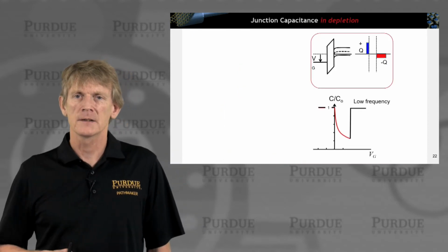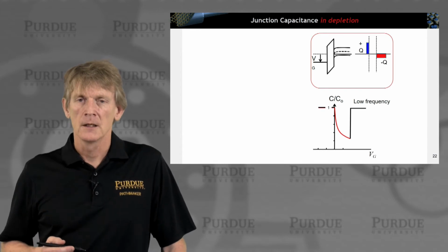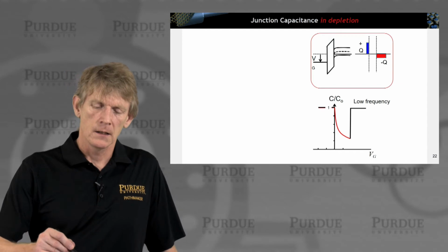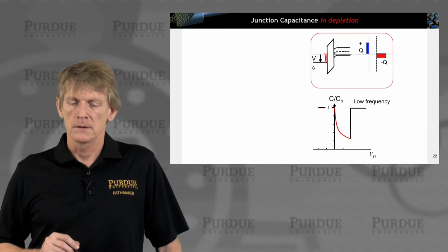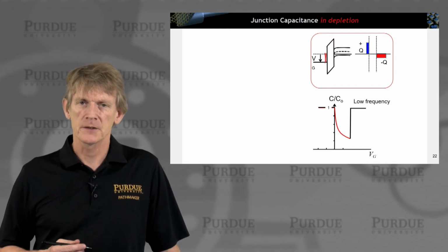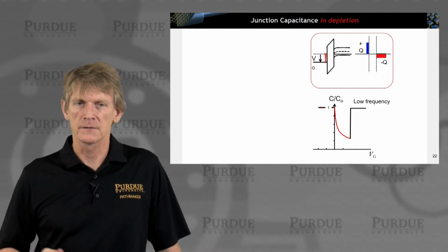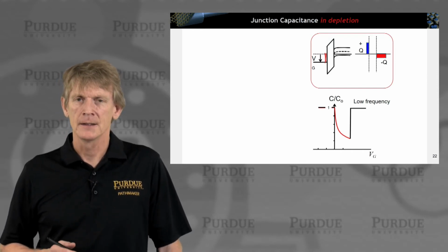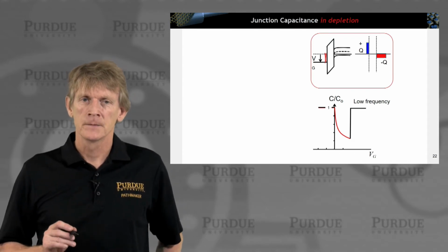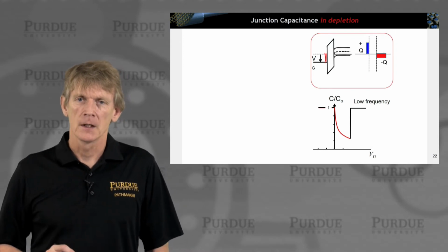All right, now let's look at the junction capacitance in depletion. We're reversing the bias on the junction. We are now having a pile of missing electrons. So we have positive charge right in the metal, induced by the positive gate voltage that we applied. There's no current flow. The Fermi level is flat. We're bending the bands, not very heavily, but we're creating a depletion region over here.